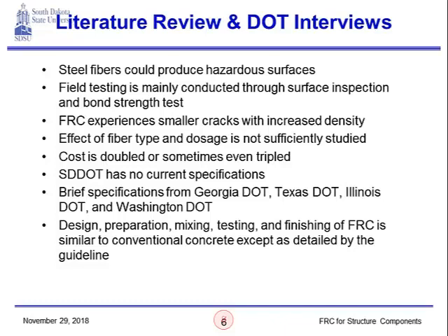But for traffic applications, it's really not a problem, as the traffic would soften these fibers with time once they drive on the surface of the concrete which had these steel fibers. Field testing is mainly conducted through surface inspection and bond strength tests. These are the only two methods that we found from the DOT interviews where they actually inspect the performance of FRC in the field, either by surface inspection or by using the bond strength test.